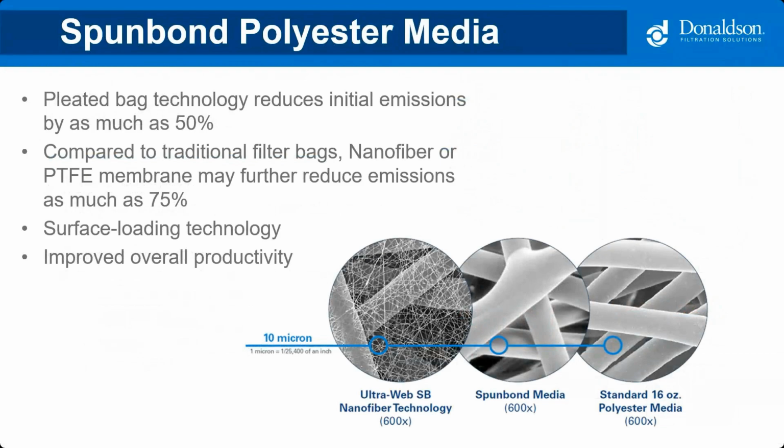So the way filters are made, a standard polyester felt, it's a needled felt, and so it's thousands, millions, however many. I've never taken one apart and counted the number of fibers, but it's a lot of fibers, trust me. It's a lot of fibers that are needled together to form a thick felt, and that's then installed on the dust collector, and all the dust is collected on it.